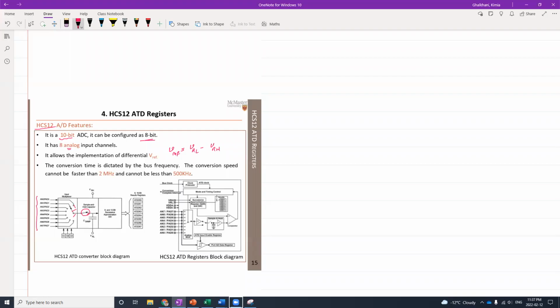As soon as this one is closed, this capacitor is supposed to get charged, right? Also this unit in here is the sampling and hold unit. Here is the successive approximation, which is also 8 to 10 bits. And remember in the lab, I said we use the 8 bit for our application, and 2 of them are free, for other applications.